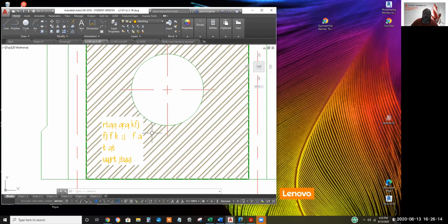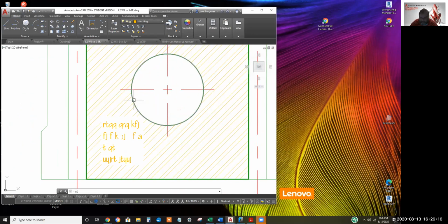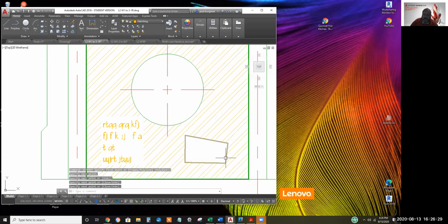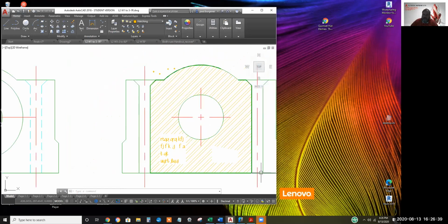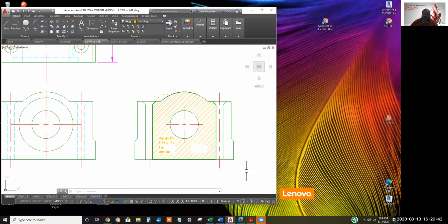There's another way, something called a wipeout. WIPEOUT, enter. I've done this a few times. I'm not proud of it. But the wipeout will kind of put a cloak of invisibility over an area. Oh, that's cool. This is one of those cheat steps for when you hear the bell of the elevator of the client coming on the floor of your building, it might be the last minute.